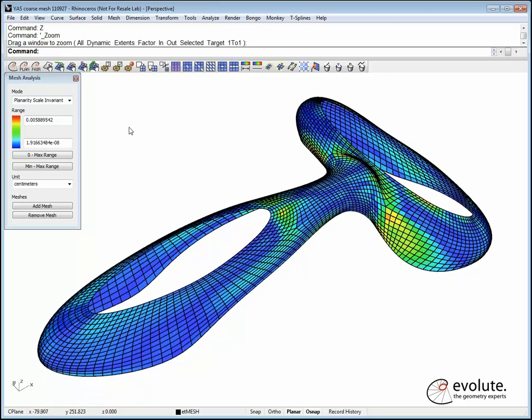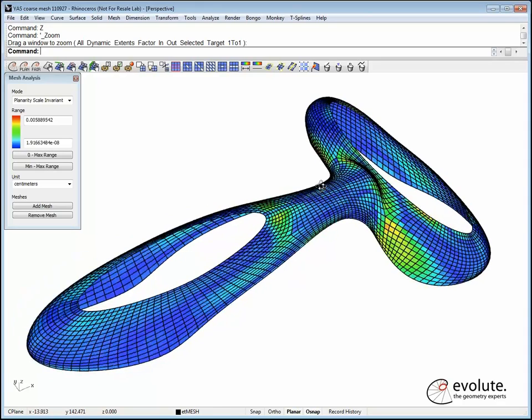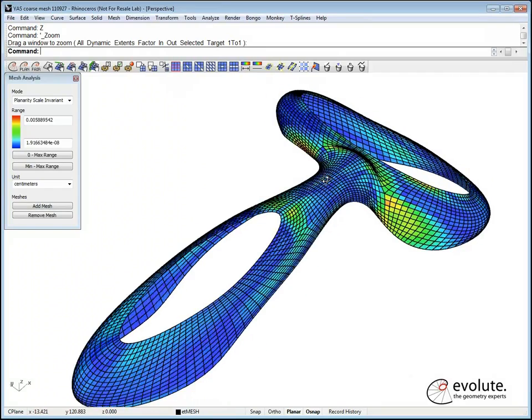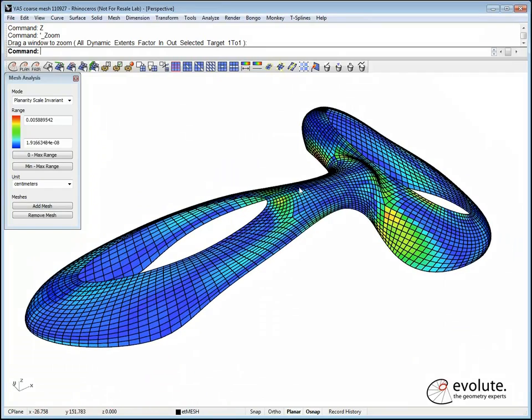Good, we played with planarity. Of course, we can optimize this further by trying to set a few constraints to relax the mesh in this area a bit, but I want to show you a lot of other stuff, so let's move on. As I'm pretty sure a lot of you know the Yas Marina appearance, it has that diagrid pattern on the shell itself, and we will achieve that in just one subdivision step.